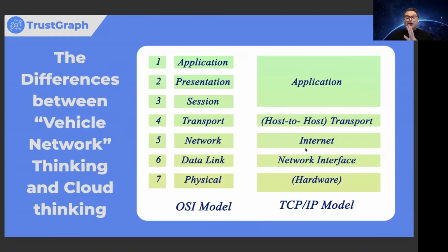And I find this really interesting. I was actually shocked. I found a graphic that had the OSI model next to the TCP/IP model. The only interesting thing is I typically have always seen the numbers go the opposite way, but I thought it was pretty good. The OSI model is actually how vehicle engineers tend to think about these networks because you control all of this. You control the physical hardware layer, the data links, the actual network, and then how you're transporting that data. And if you're using federated networks, you have a lot of networks going on, and that's kind of where things like DDS pub/sub, which we're going to talk about, come in.